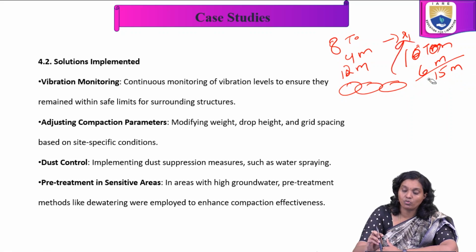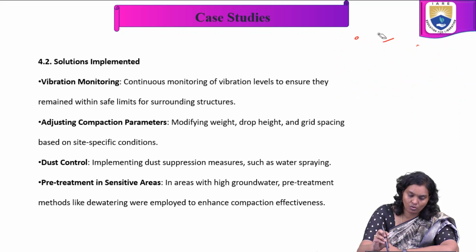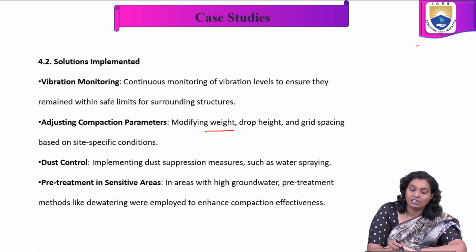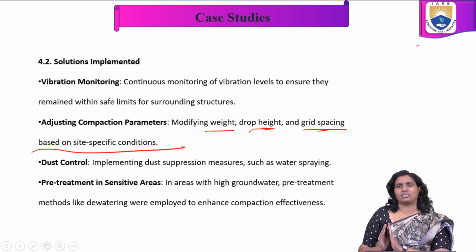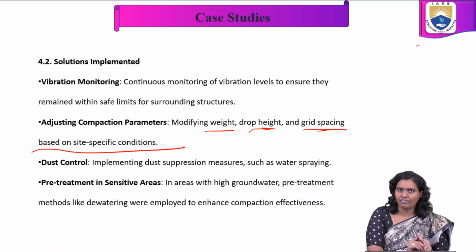Like that, we have to maintain the uniformity of the compaction by adjusting the compaction factors, modifying the weight, drop height and grid spacing based on the site-specific conditions.